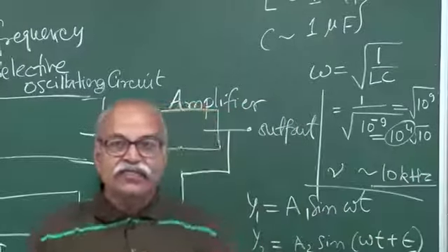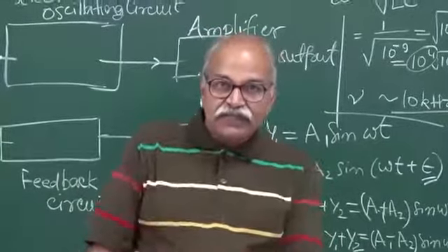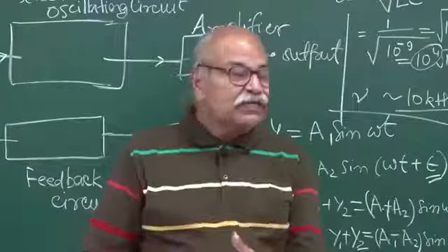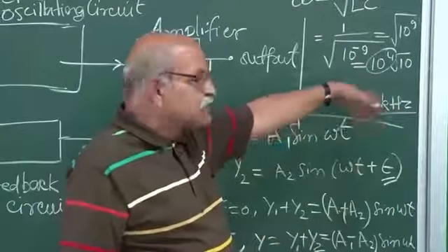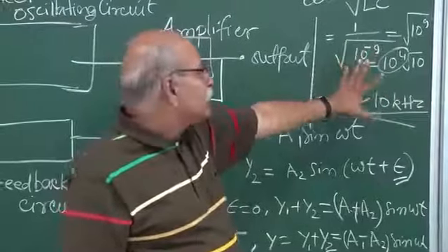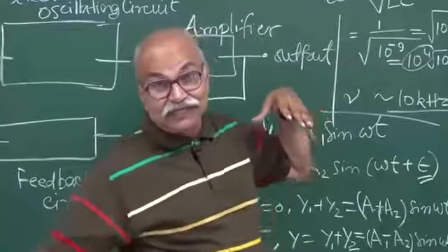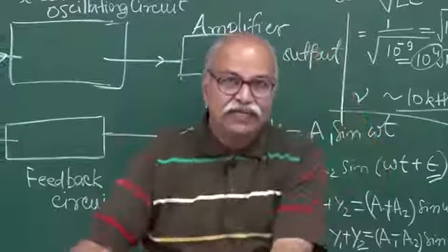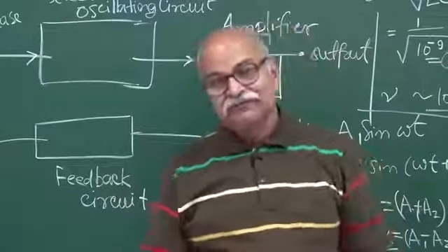So in this oscillator that I showed you, it had a low frequency range, high frequency range, middle frequency range. So that LC oscillation that I had described can be used in this middle frequency range, which is around kilohertz, 10 kilohertz, 100 kilohertz, like that. So for that, this LC thing can work, but for lower frequencies or higher frequencies, something else has to be used, and that must have been used in this box.